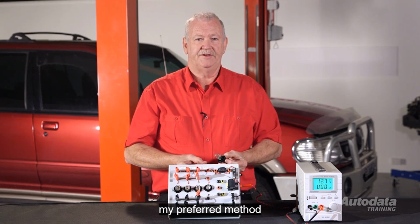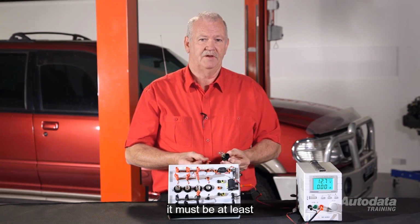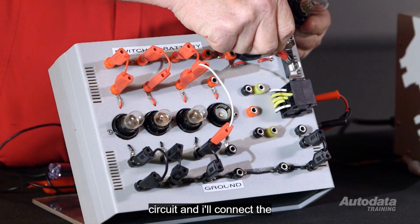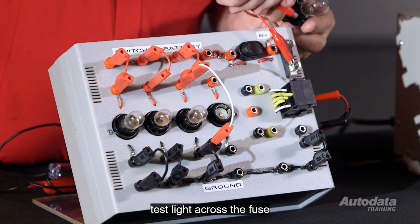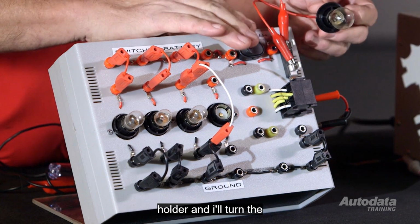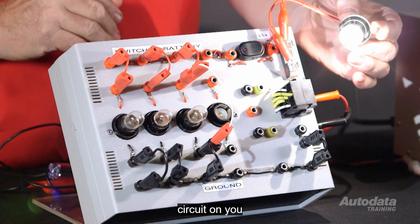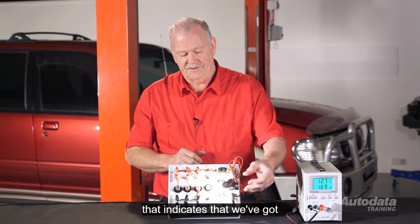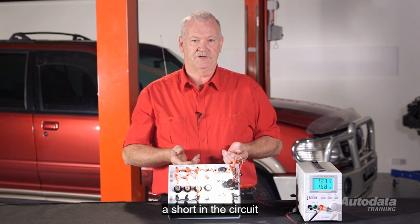My preferred method is using a test light. It must be at least 21 watts. I've got the fuse removed from the circuit, and I'll connect the test light across the fuse holder. And I'll turn the circuit on. You can see the light is glowing bright. That indicates that we've got a short in the circuit.